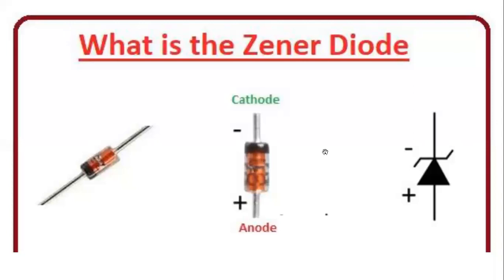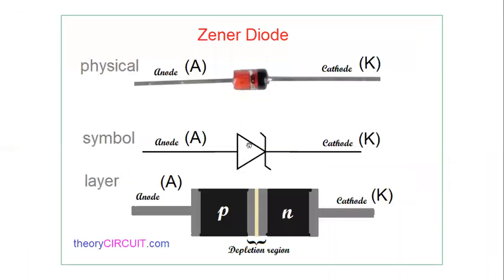I was asked what happens if the Zener diode is forward biased. For a Zener diode and a main diode or ideal diode, there is no change, my student. When you forward bias, it is the same as an ideal or practical diode. When it is reverse biased, it is also the same. But when it crosses the Zener voltage, a specific voltage that is written, at that time it becomes a voltage source. Am I clear, Mohammed? Yes, sir.